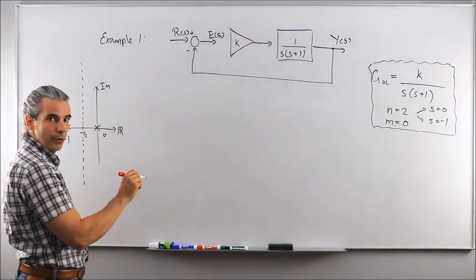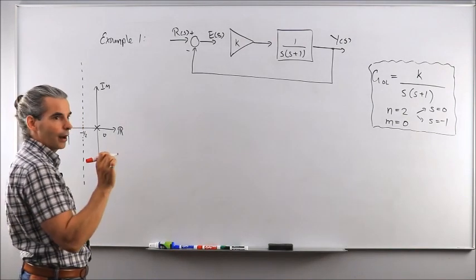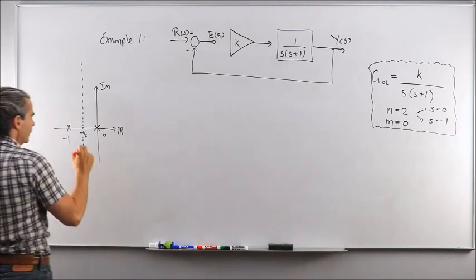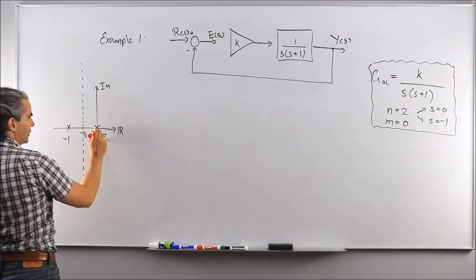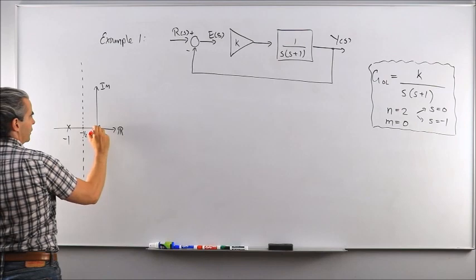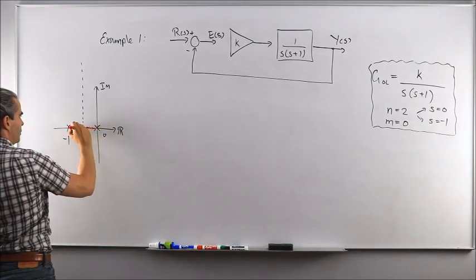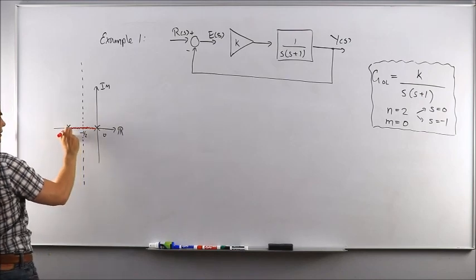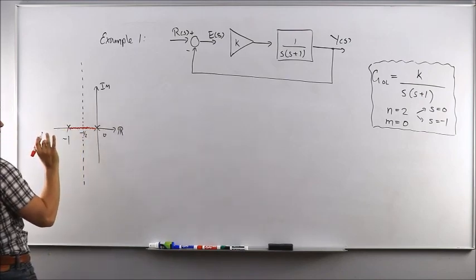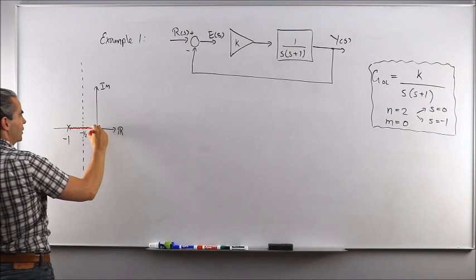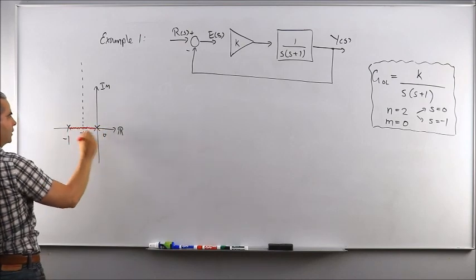And if the number becomes an even number, pen up and you stop drawing. I'm starting at the origin. There's already something there, so that's 1. 1 is odd, pen down. Then the second object, pen goes up, and I stop drawing there. Meaning that the root locus will be comprised on the real axis between those two poles.